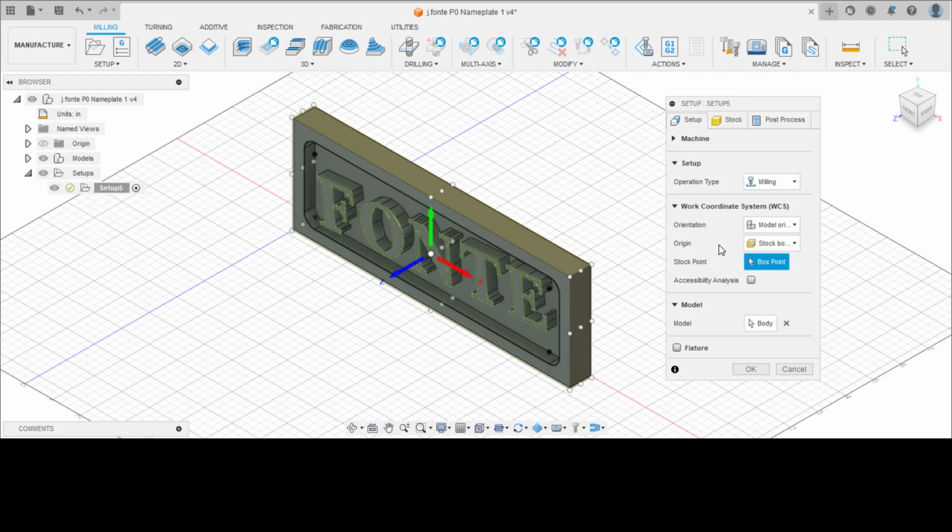You're also going to set up your absolute zeros for your X, Y, and Z. So we want to make sure that our X axis is running along this plane right here, our Y is running along this axis here, and our Z is actually coming off of the machine. The Z is the actual cutter, the tool that's going to come down and cut out our work. Mine is set up correctly. I've got my X pointing this way, my Y pointing straight up, and my Z pointing away from the machine.